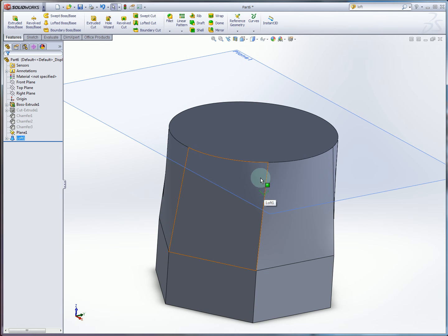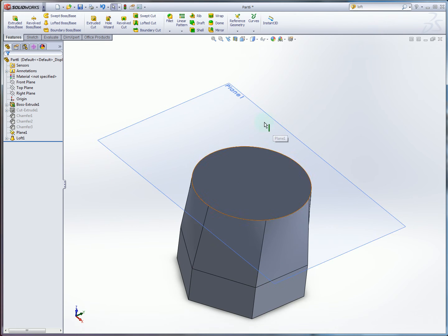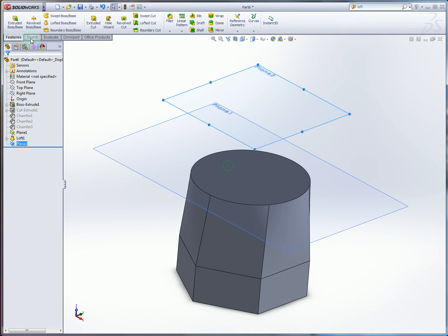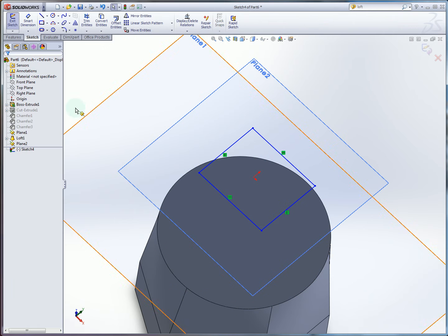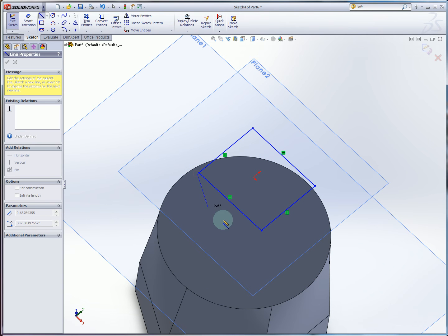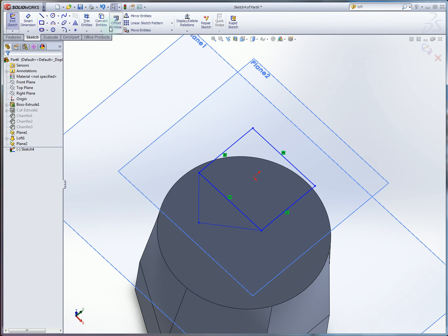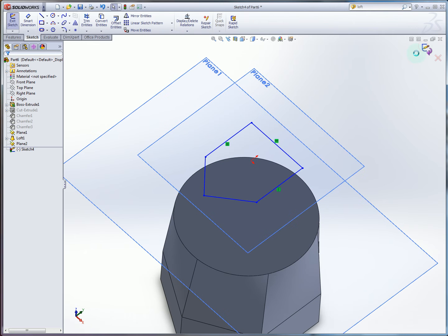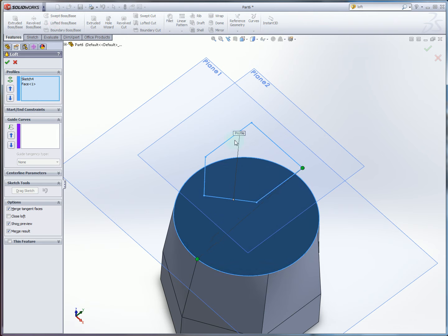And you can do this with multiple sections. You can do it between a round and a square. So for example, if I do yet another reference plane, and I will draw a sketch on here, you can see even if this sketch is fairly exotic looking, it should still be able to solve. So I'll do like this home plate shape, still of course constrained to have a closed section. And with this sketch and this top surface, I'll create another lofted plane.